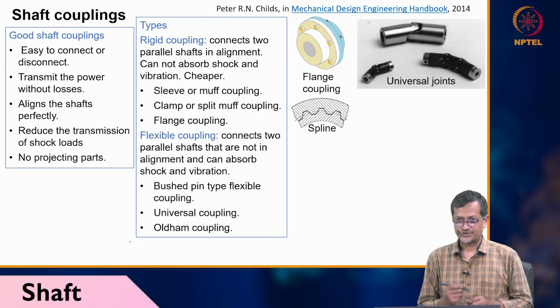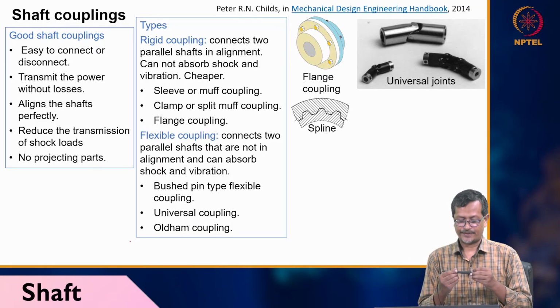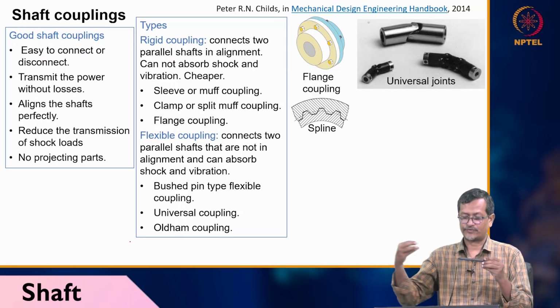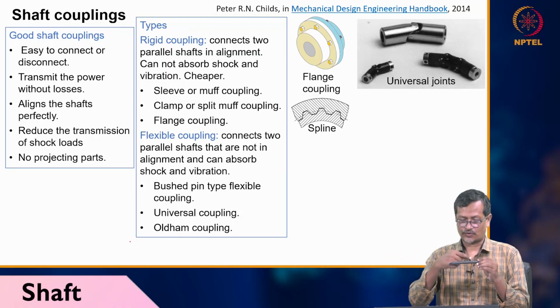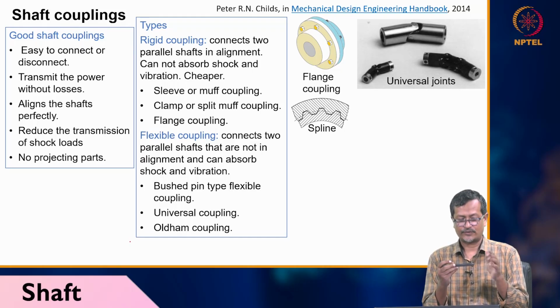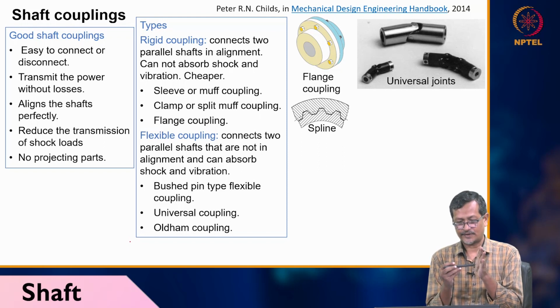When you have two shafts, one shaft cannot be manufactured because several issues are there. What is happening? One propeller is here and your engine is here, and you are transferring power from the engine to the propeller. So the engine is transferring torque. The shaft's main purpose is to transfer torque, but with the propeller, what is happening? When it is rotating, it is pumping fluid, giving energy to the fluid, so the fluid will react. It gives a reaction force to the propeller, so the propeller will transfer that force to the propeller shaft.